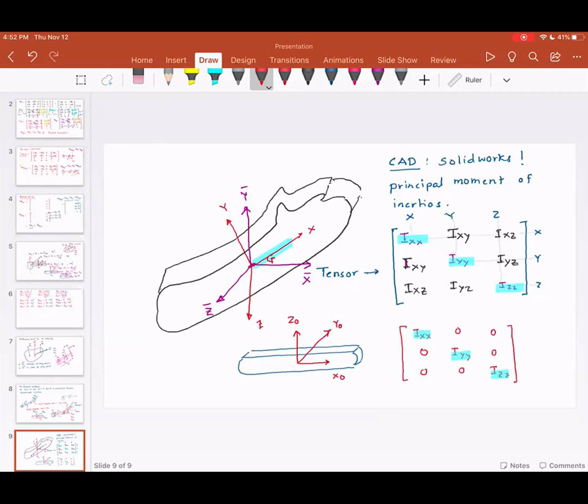But when we go to Robotics 2 and come up with the dynamic analysis for a practical robot arm, we will go to the CAD model in SolidWorks. We will look at the different inertias that are reported by the CAD software and see which inertias to pick. This is super important: depending upon the axis that you choose, your moment of inertias would be different.